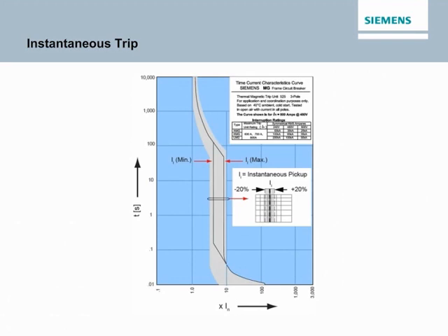This circuit breaker has an adjustable instantaneous trip point from 3250 to 6500 amps, which is approximately 4 to 8 times the 800 amp continuous current unit rating. This adjustment affects the middle portion of the trip curve, but not the top or bottom parts of the curve. The breaker shown in this example has a thermomagnetic trip unit. Circuit breakers with solid-state trip units typically have additional adjustments.